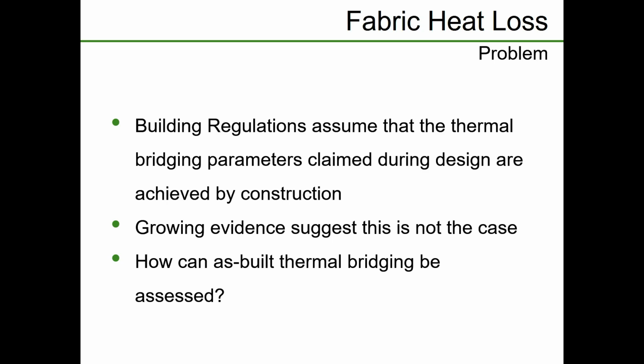So if you measure the heat loss from an entire building and you measure all the component parts as well, and you subtract that, what you should be left with is thermal bridging. But then how do you look at the individual thermal bridges? And that's what we're doing here.